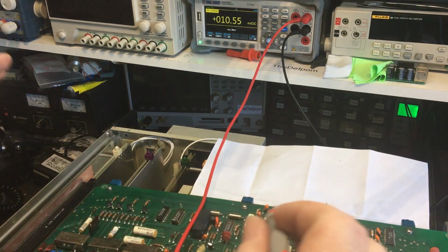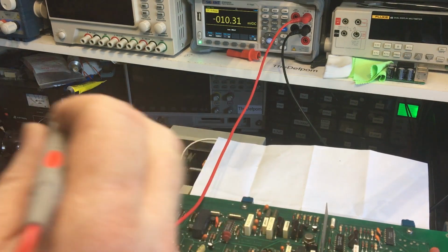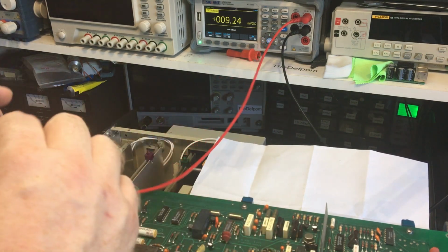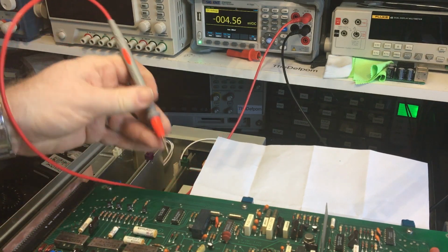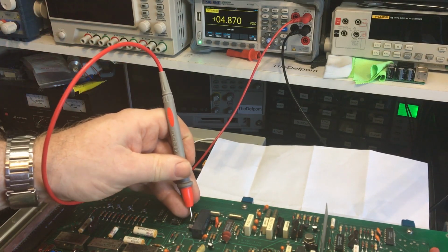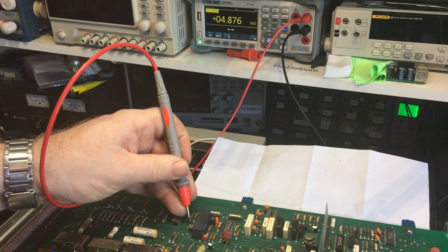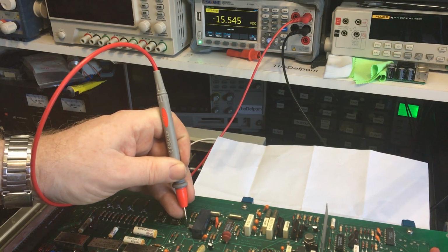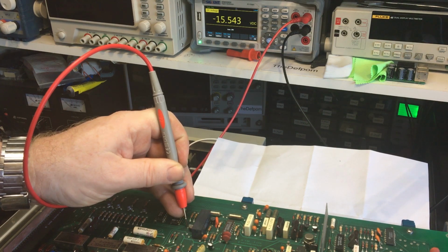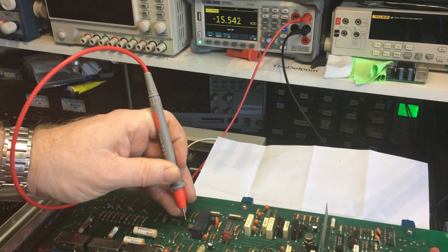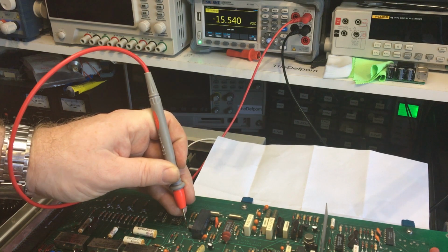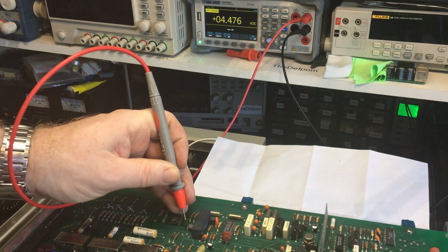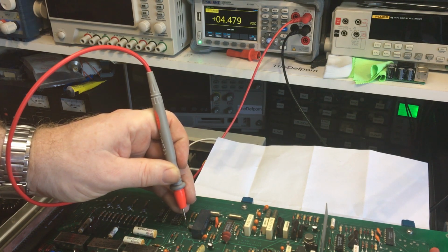Now bear in mind, I don't have any signals being fed into it right now, but I will test the switching characteristics of these devices. So I need to figure that part out. I'm not sure what the pinout is on this particular device. So I've got 5 volts on that pin, 5 volts on that pin, minus 15 on that pin. So minus 15 will be the coil side, which means that's currently off. If I change this to external phase lock, it goes positive.